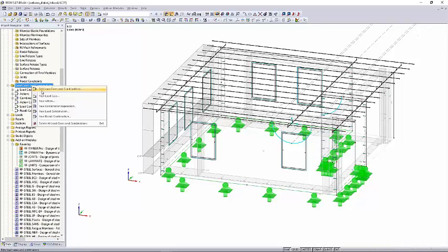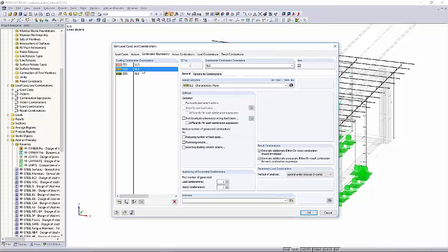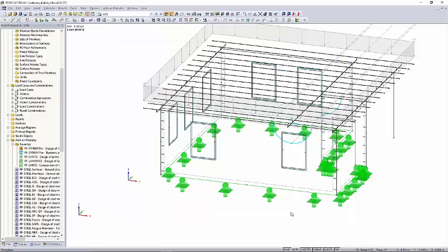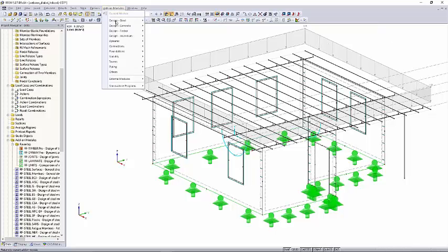A quick look into the load combination expressions. I will just concentrate on ultimate limit state, not on the serviceability. I will do an analysis according to first order theory, and this gives me these load combinations that are done automatically. And now I will create a stiffness in the add-on module laminate.